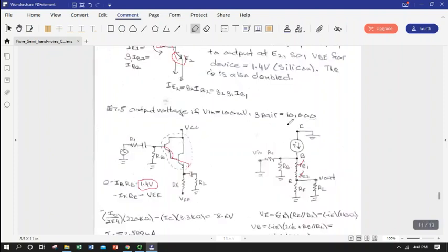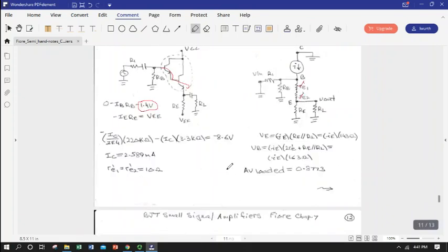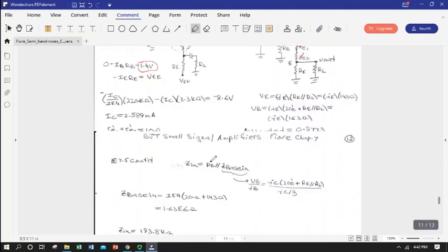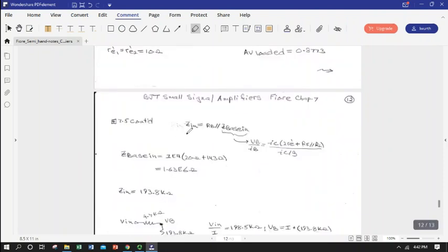The biggest effect comes from a great big beta, 10 to the fourth. And that will be felt in our input and output voltages every time we have that beta multiplier on one of those parallel components. We'll now either drastically increase something or drive it into the ground. So that's the Darlington pair being used as the actual BJT component of a common collector.